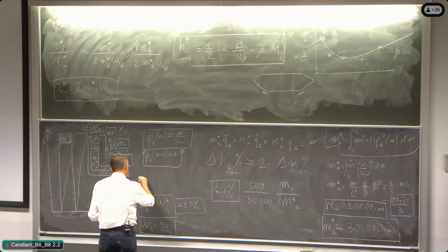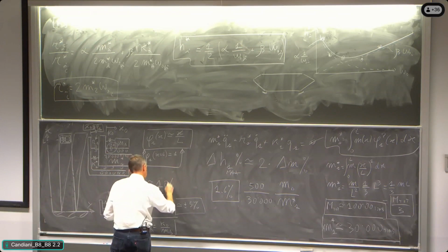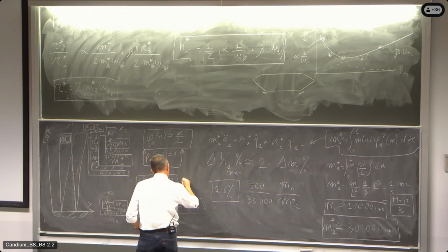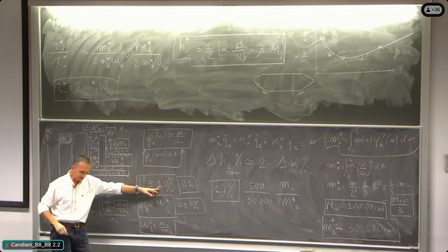Then, second hypothesis, the non-dimensional damping of the damper is about 10%. So the best tuning, so it is 0.1, non-dimensional damping equal to 0.1, that is 10%, all right?